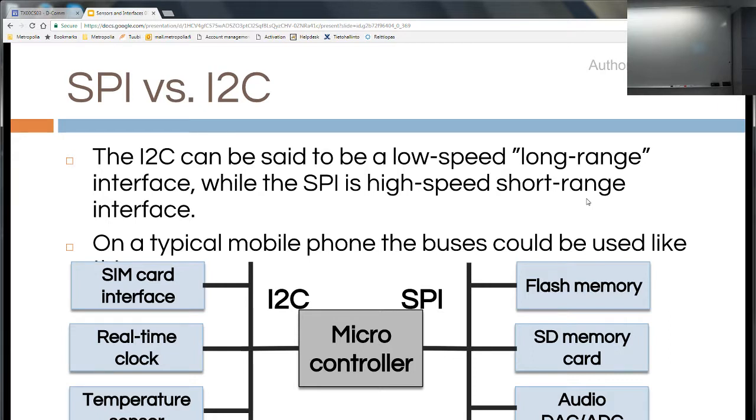So basically, usually in a microcontroller environment you can find some systems on the I2C bus and other systems on the SPI bus. SPI bus is nice because it can be very fast. Flash cards or those SD cards, actually, those use the SPI bus to transfer the data.